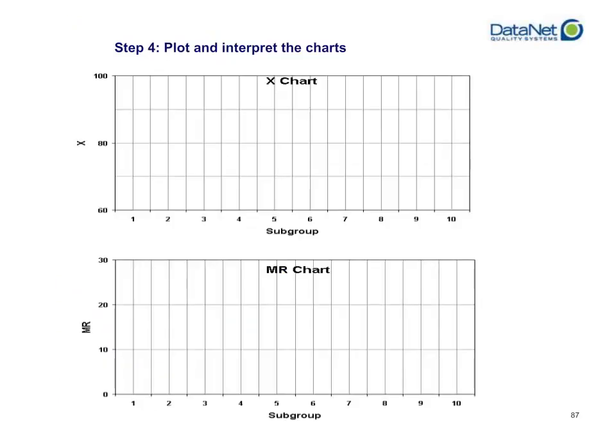I'd really recommend, again, plotting your control limits first and taking care that the scaling is going to give you some room to actually plot your points on whatever grid you choose to use. If you use the SPC Fundamentals training guide, you should be given enough room in the example areas to properly plot all of these points. After you plot the control limits for both your primary X chart and your secondary MR chart, then go ahead and plot your individual samples that you calculated in step 1.